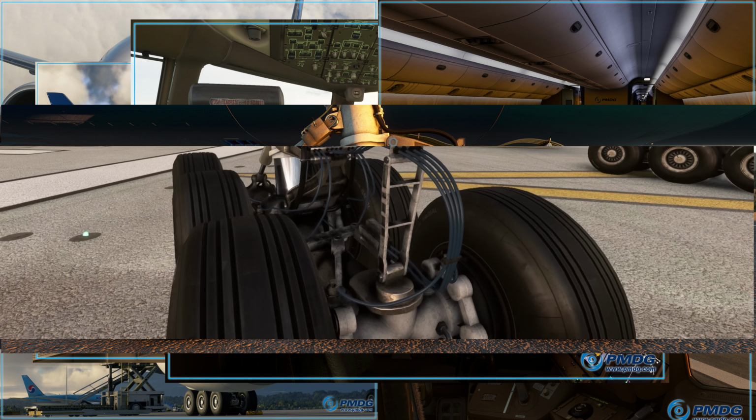And for that reason, since the doors are going to remain open, it is also going to get quite a bit louder in the cockpit when an alternate gear extension has been done. Now, of course, alternate gear extension is fully modeled in the PMDG 777, including all the effects that it has on the entire hydraulic system and on the supply to the different systems.